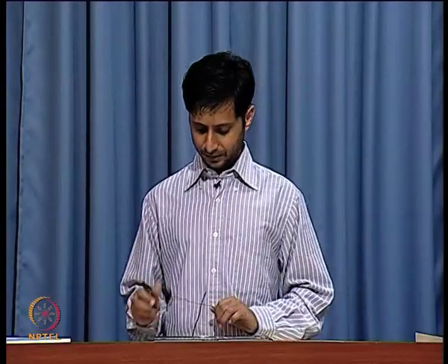All right. Now, ours is reverse biased. The higher you make the source voltage, the higher you make the drain voltage, the more reverse biased it is going to be, and the capacitance is going to decrease further and further. All right. So, that is fine.